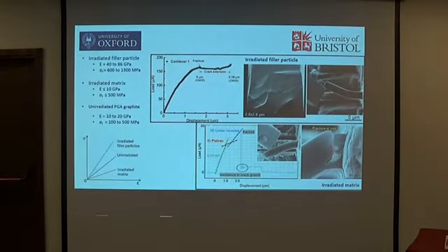So here, quickly, I'm just showing one example of the irradiated filler particles. If I look at the load displacement curve, it goes up linear, then it's non-linear. When the fracture happened, I saw the fracture from the SEM, but the load doesn't drop, it carries on going. I don't want to overinterpret the data, but this tells us that after irradiation, graphite somehow becomes more resistant to fracture.